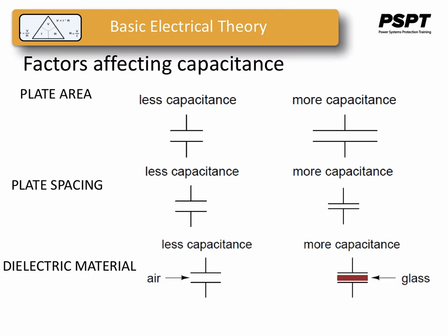Although it's complicated to explain, some materials offer less opposition to field flux for a given amount of force field. Materials with greater permittivity allow for more field flux. Others offer more opposition and thus a lesser collected charge for any given amount of field force, applied voltage. Relative permittivity means the permittivity of a material relative to that of a pure vacuum.